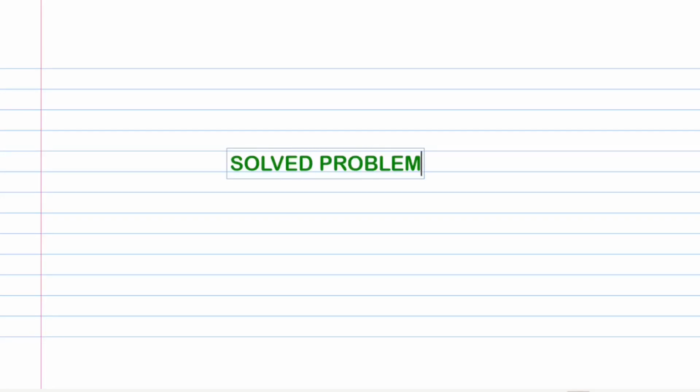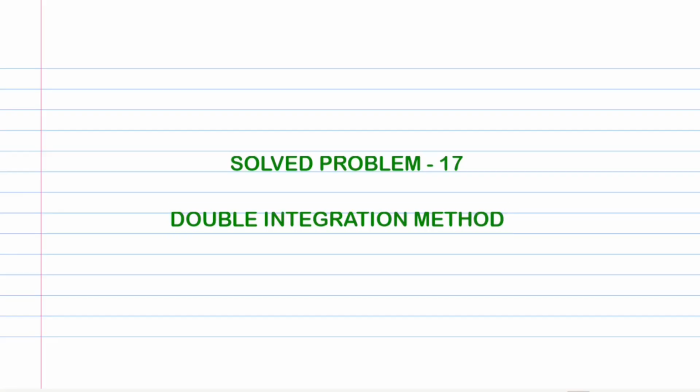Welcome. In this lecture, we shall look at the use of the double integration method to calculate the slope and deflection for the case of a cantilever beam. We shall initially consider the cantilever beam loaded by a single point load at the free end, then by a uniformly distributed load over the entire length, and finally with both loads superimposed.